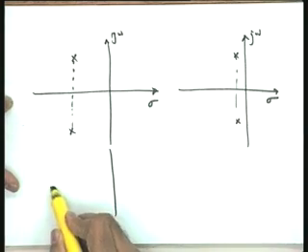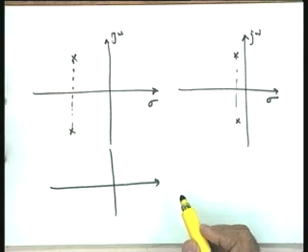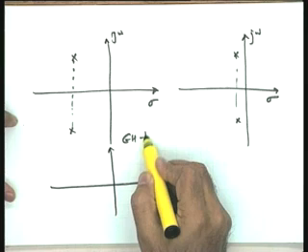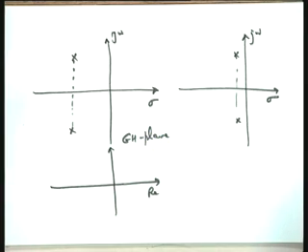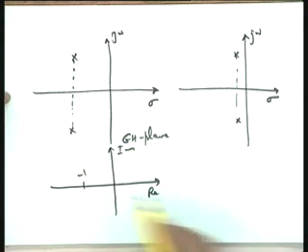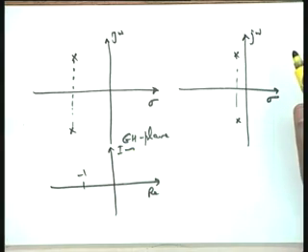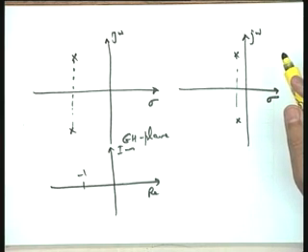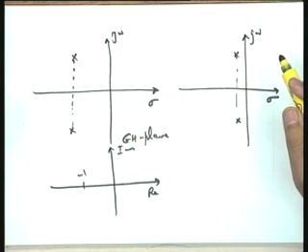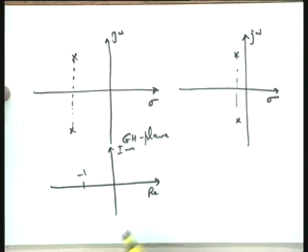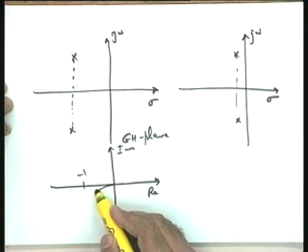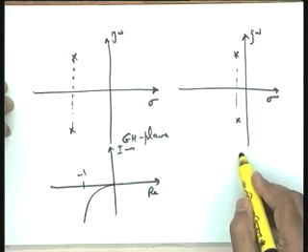In the frequency domain, if I consider this system and make a Nyquist plot of it, this is now the GH plane, that is the G(s)H(s) plane, where GH is the open loop transfer function of the system. So, this is the real part, this is the imaginary part, this is -1. When I say the Nyquist plot, primarily it is the polar plot, because its mirror image about the real axis, and then closing the path, will give you the complete Nyquist plot. In this particular case, I expect that the plot will be of this nature. Just as an example, the plot will be of this nature, while in this particular